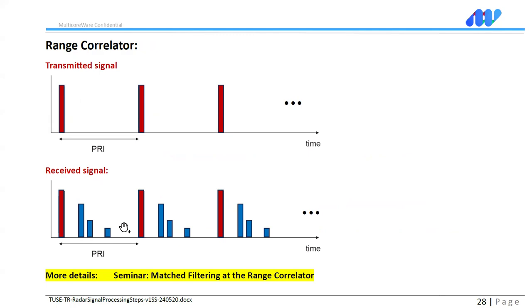And if we have 3 targets, we see 3 reflections. Assuming they have the same size, as a function of time, it goes to a further point, so we expect the amplitude to go down, because the farther you go, the weaker the reflection is. And that's, again, the topic of match filtering.